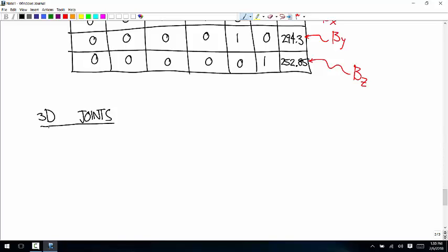And then we went through all the other possibilities for reducing degrees of freedom. We talked about joints that restricted all translation but allowed rotation. And then, since there's only 3 possible degrees of freedom in 2D, the only thing that was left was something that restricted all translation and all rotation. Okay, so only 3 possibilities.